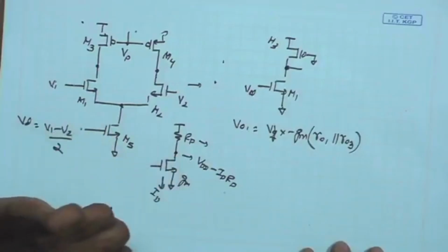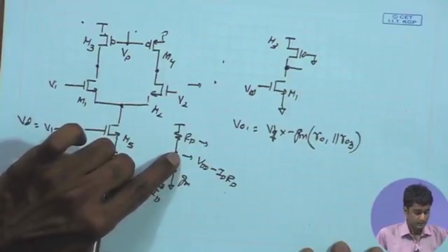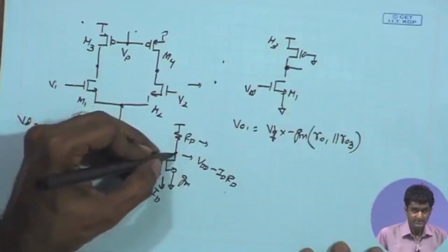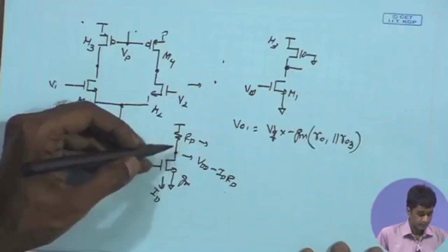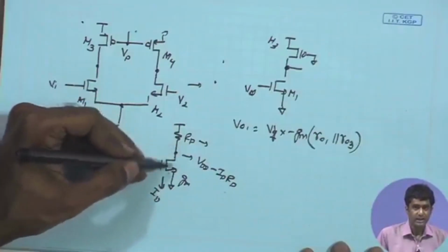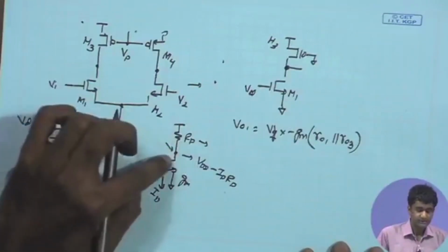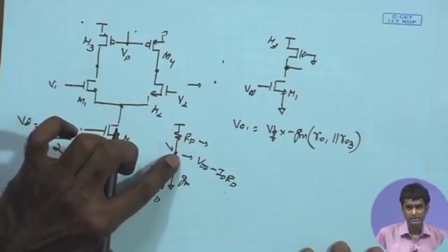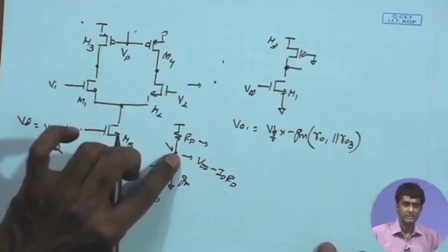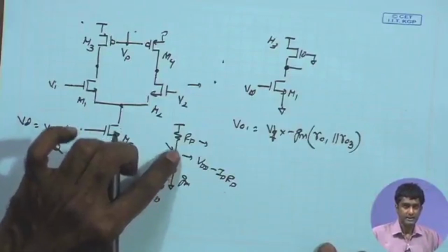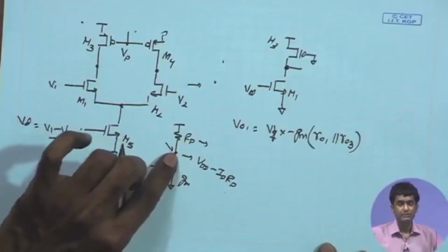And I know that for a symmetric swing or maximum possible swing, I should bias this DC point at the output close to the midpoint of the maximum and minimum allowed voltages. So in a circuit, if you find out the maximum allowed voltage at this node to keep the transistors in saturation, and correspondingly the minimum allowed voltage, that gives you the range of the signal swing that you can have at this point, and a good DC bias point would be the midpoint of that.